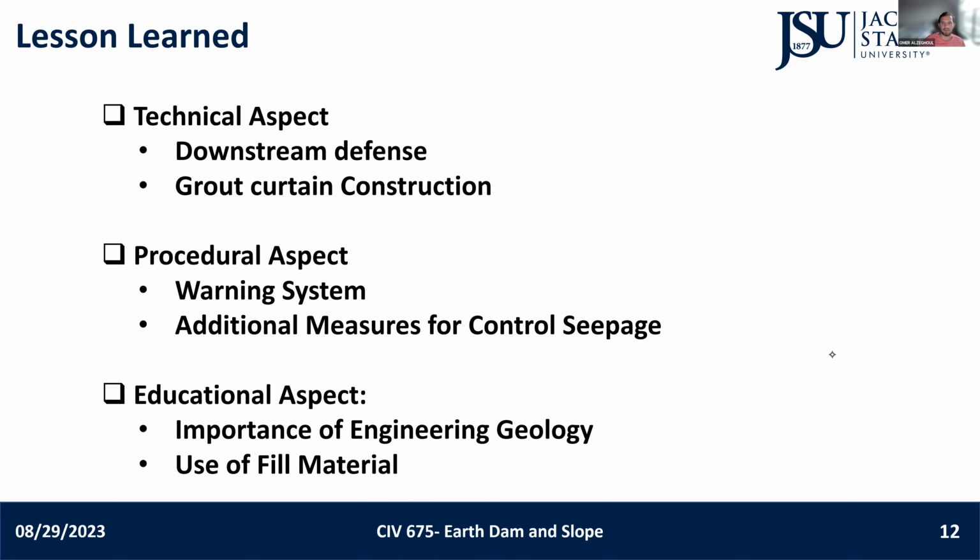It was a design issue, right? It was the design of the dam. Basically, what went wrong? From what I see from the picture, the hole was high. It was not at the base of the dam. It was almost above the middle of the dam. Few things took place. First of all, they didn't study the whole geology. That investigation was poor. Secondly, they started filling the water. For the first 6 months, it was good. They put in about 160 feet of water, and then within 1 month they put in 150 feet more. After that, within 2 or 3 days, this incident happened.